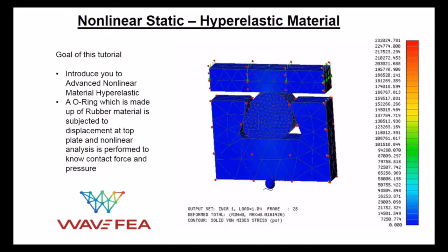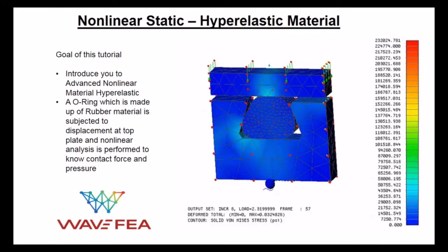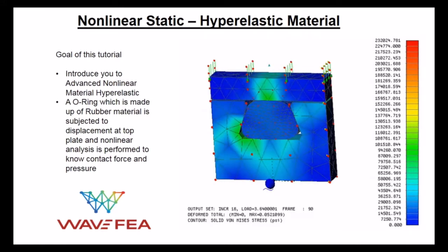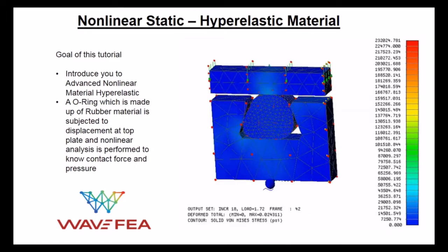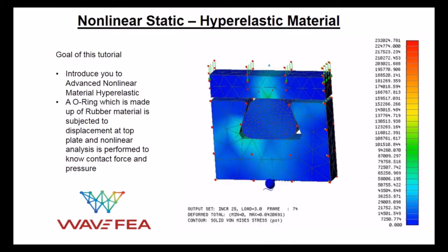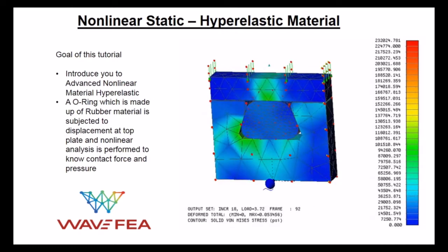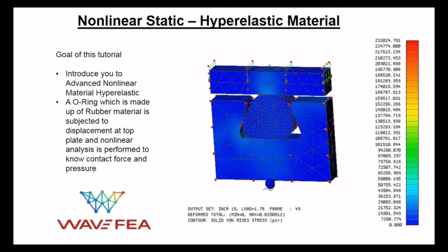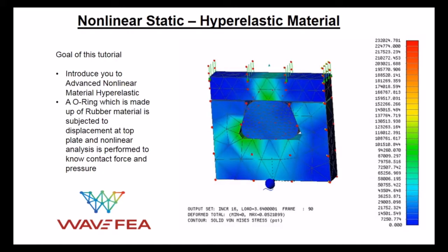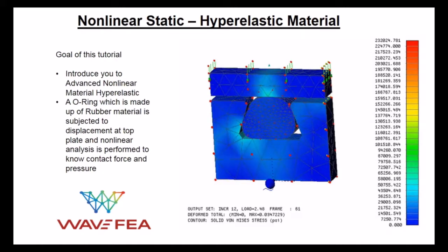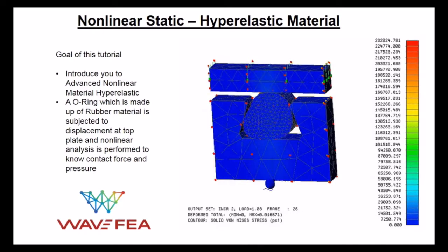Hyperelastic material is still an elastic material, which means after the removal of forces, it will retain its original shape. It's also a Cauchy-Elastic material, implying that the stresses are determined by the current state of deformation and not by the path or history of the deformation. Hyperelasticity provides a means of modeling the stress-strain behavior of such materials.